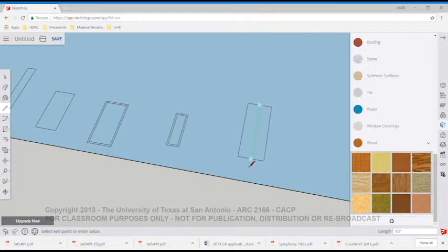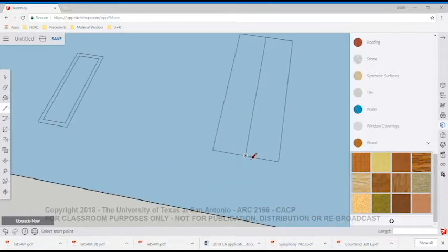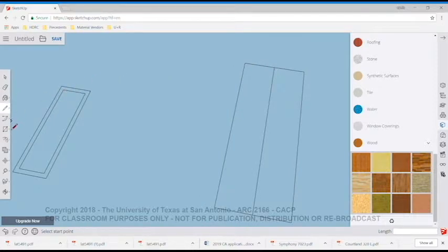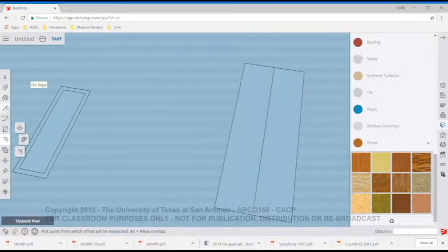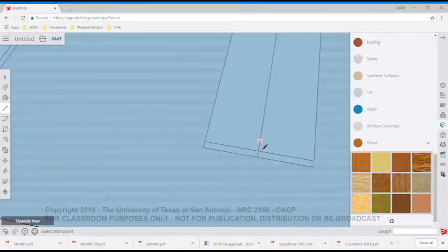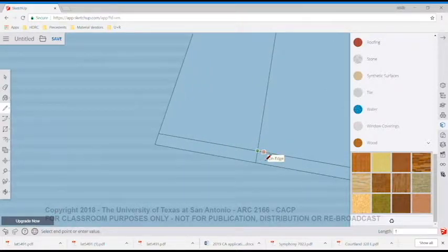So a wide flange doesn't have the hole in the middle. It's got essentially that hole distributed about the sides, and it's kind of structured in a really particular way. And we use the offset tool. We kind of want the edges to have about a 1/4 inch edge, so we'll just draw it 0.25 inches. And 0.25 inches. SketchUp is remembering what it thinks I want it to do. And then in the middle, it's usually thinner, so I'm going to go 1/8 of an inch over.